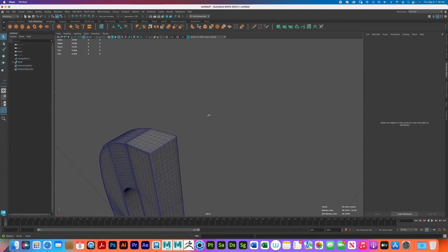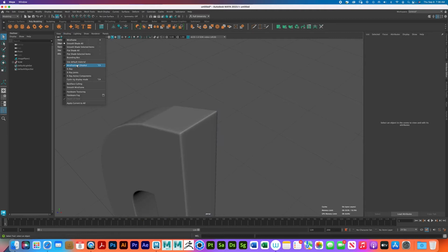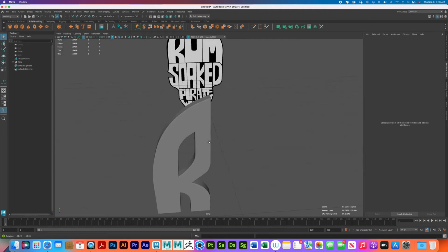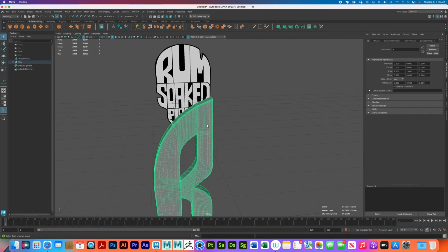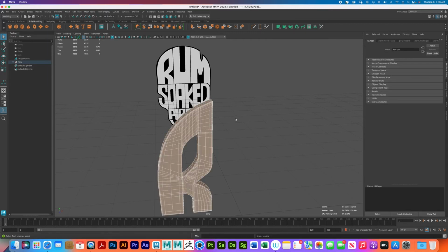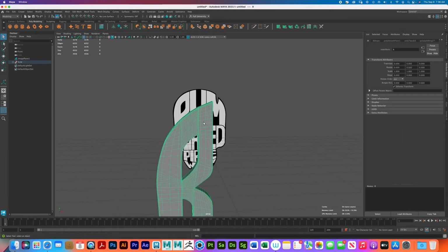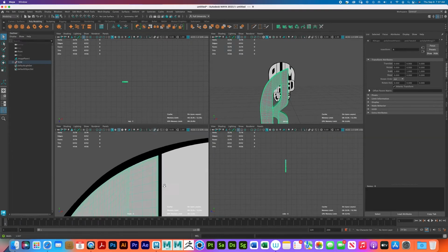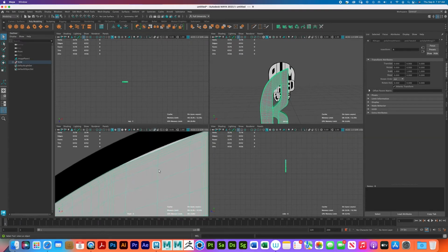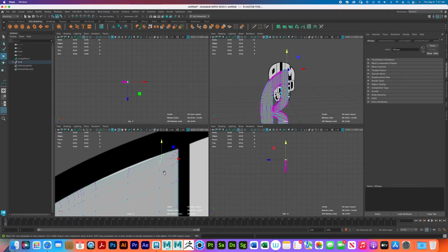Even if it's heavy, if I take away the wireframe and shade it, it's okay. It's what I want, right? So let me go back. I don't want that; I want it smooth enough for me. And again, if you have a situation where you're not happy, let's say you don't want that sharp edge, guys, take your time. Take your vertex, press W, and work those kinks out. Never settle for something that you're not happy with.